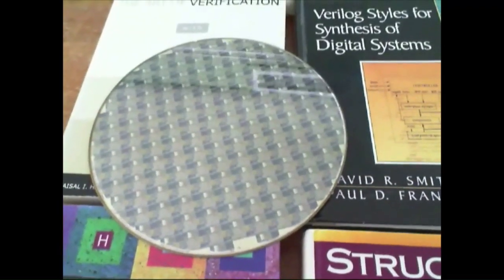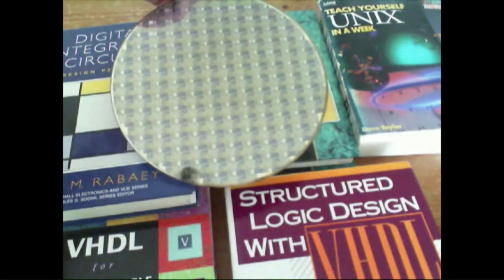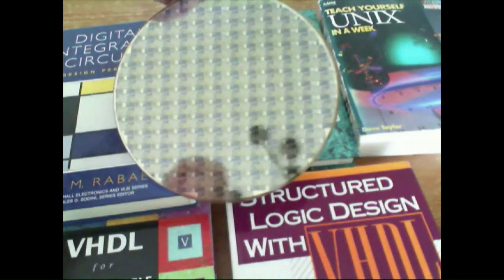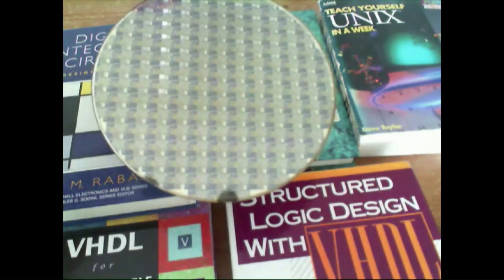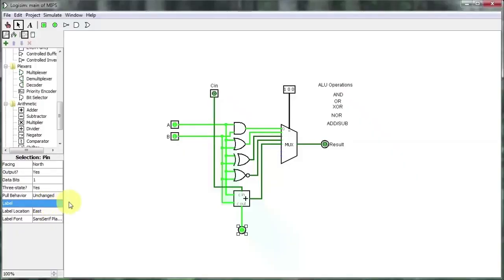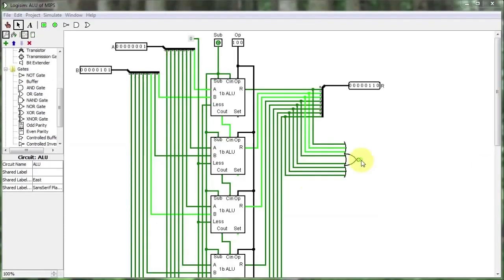Legality incorporates such constraints as the circuits not overlapping one another and remaining within the bounds of their placement area, being placed in valid orientations and in rows specified in the chip image, satisfying other restrictions supplied by either the user or the technology.